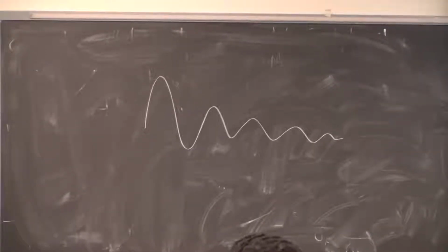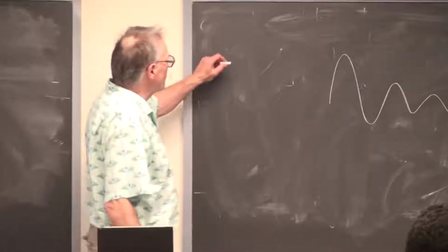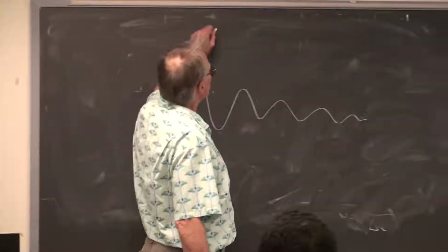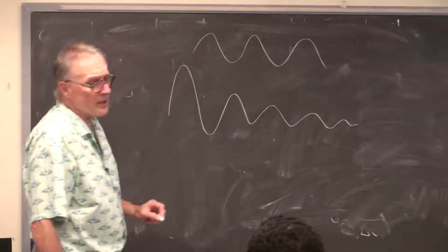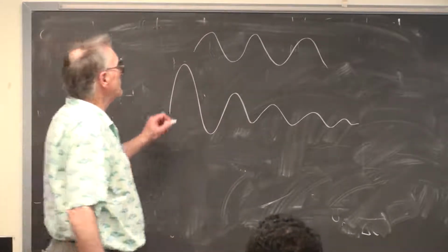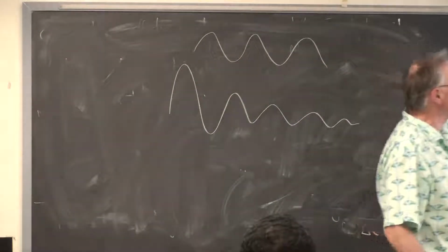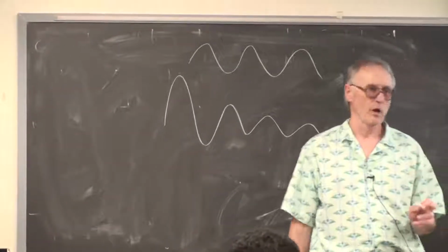And then you don't even have to turn it off. It just auto turns off. If you are going to put out a sine wave burst for a half a second or a second, you probably can't make a table long enough to do that. You'll run out of memory. And so you're going to probably put the DMA channel in auto mode. It depends on the effect you want.